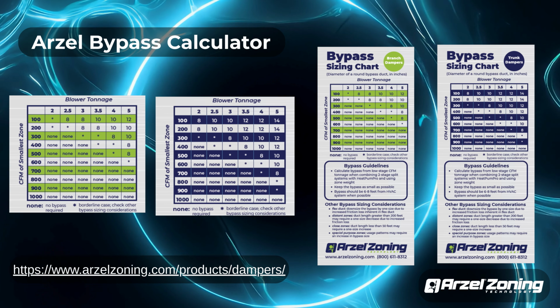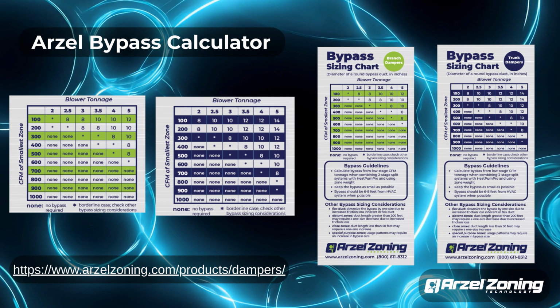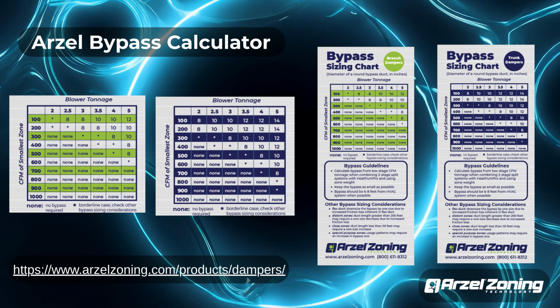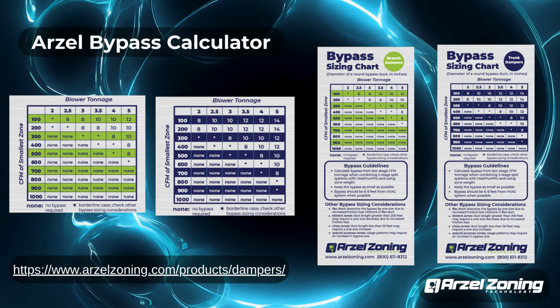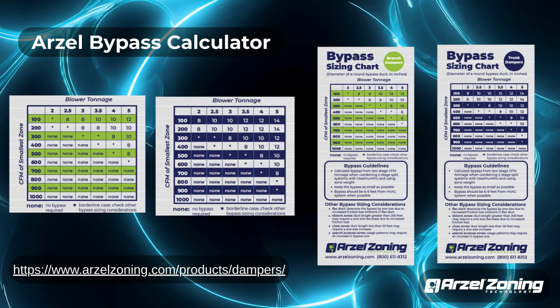The Arzel bypass calculator, you should have one of those. So if you look at that bypass calculator, there's a few things I want to point out. One side is marked in the green circle at the top right. It says trunk damper or branch damper. There is a separate calculation for trunk dampering, and so there's a different calculation based on whether you're doing a trunk damper or a branch damper system.